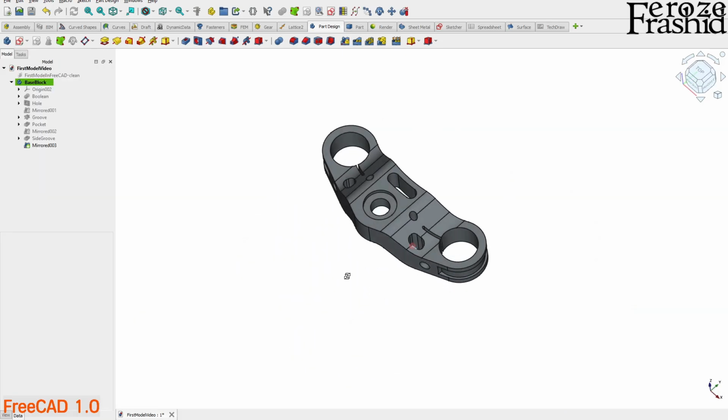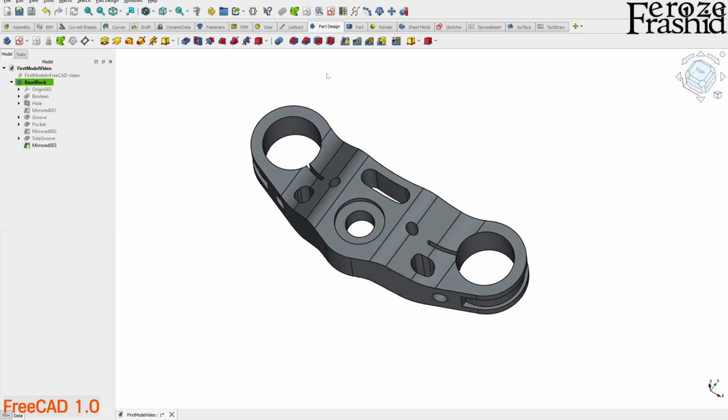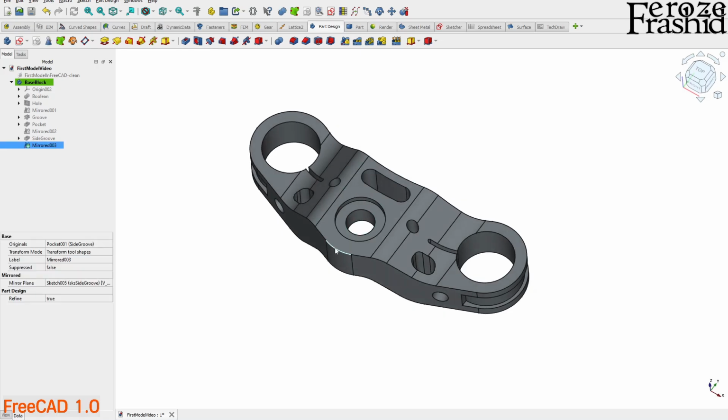All right, that's all the features that we needed, except some chamfering and filleting. Filleting is rounding the edges. Chamfering is making a plane at an angle. So filleting, let's do that. Select this edge. This is the fillet button, and there's the chamfering button, the two most used dress-up features. When it comes to chamfering and filleting, if you select part of an edge that's continuous, it's equivalent to selecting the whole thing. So we just selected it, right?